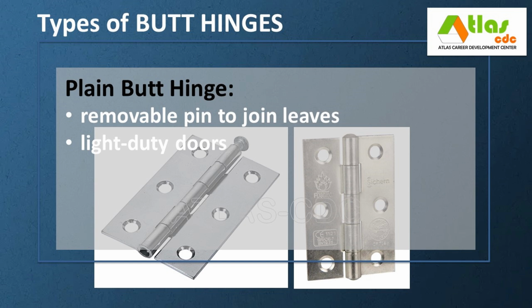These plain butt hinges consist of two interlocking plates, leaves, joined by a central pin and knuckle, with no added friction-reducing elements such as washers or ball bearings. The metal-on-metal contact is suitable for light-duty door hardware requirements, including closet doors, interior passage doors, and storage room entries. However, due to their basic construction, plain butt hinges are not recommended for exterior or high-traffic applications. They are best suited for very light-duty residential or office doors where smooth, budget-friendly operation is a priority.